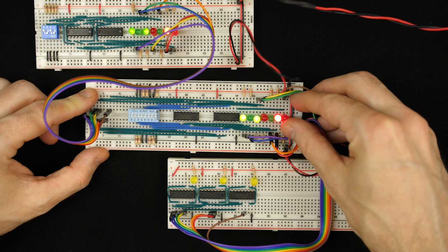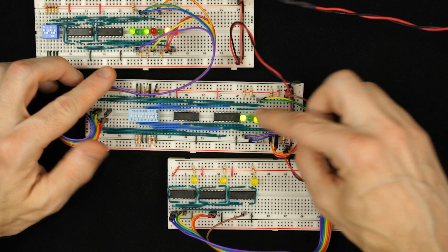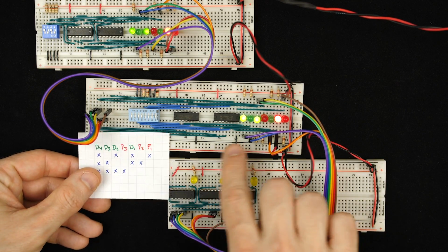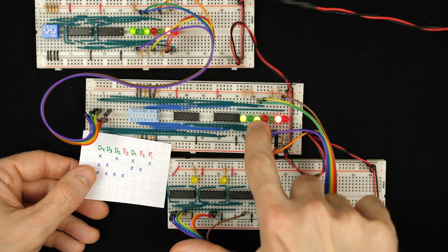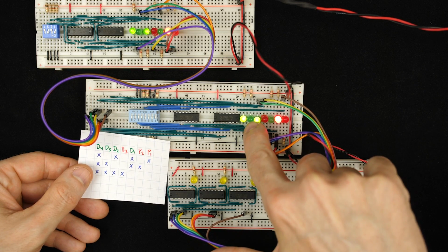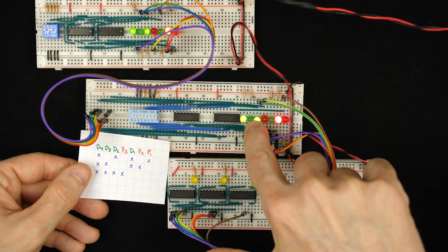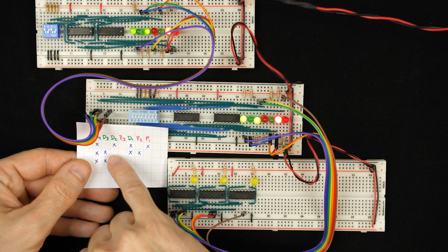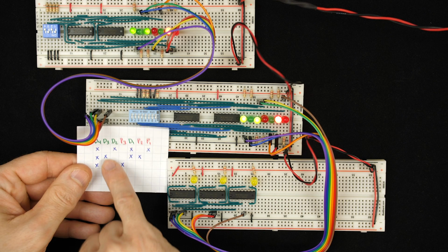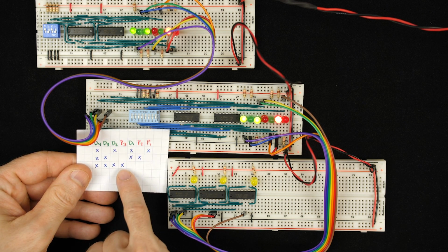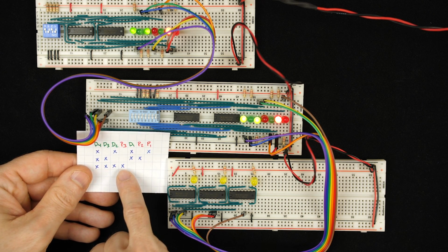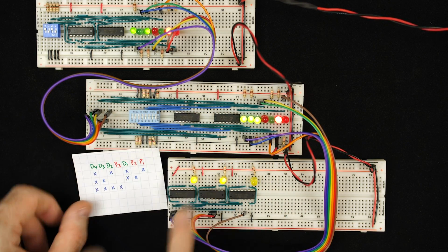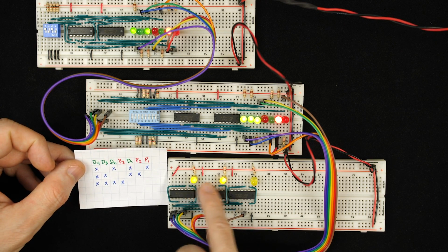So right now we don't have any errors injected, so all of the parity bits check out. But let's say we were to inject an error. Let's say we're going to inject an error into bit 3. So right now, bit D3, the second bit here, is off. Let's say that some sort of error occurs that flips that on. Well, that's going to screw up these 2 parity checks here, the parity check for bit 2 and the parity check for bit 3. So let's do that. If we flip that on, now we see that those 2 parity bits are wrong.